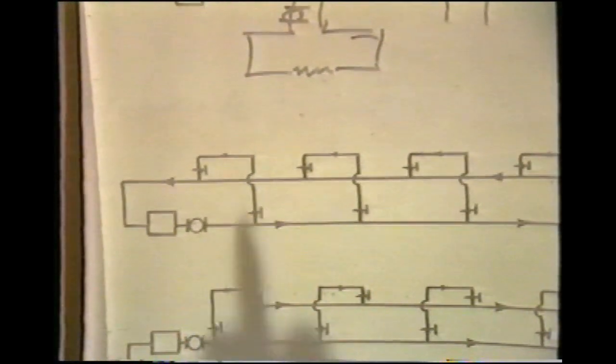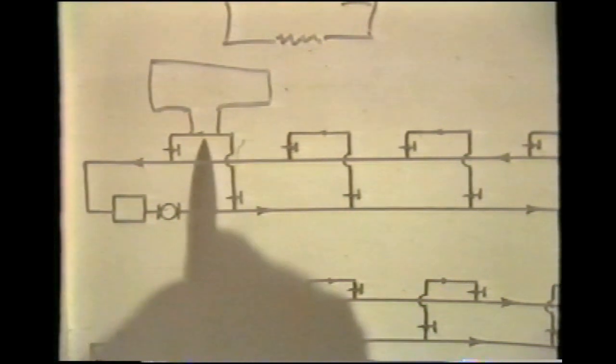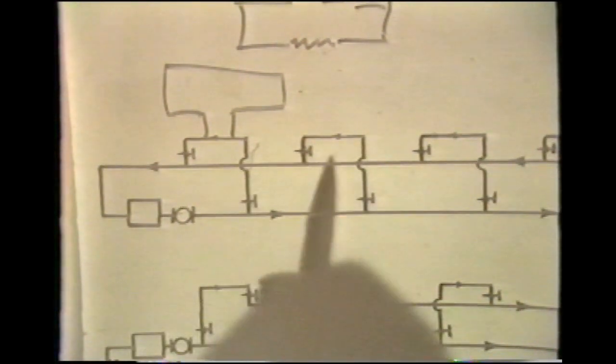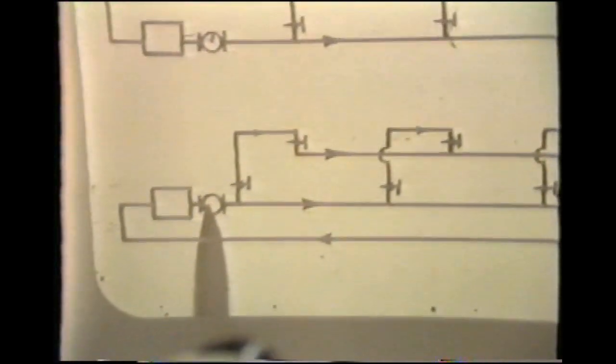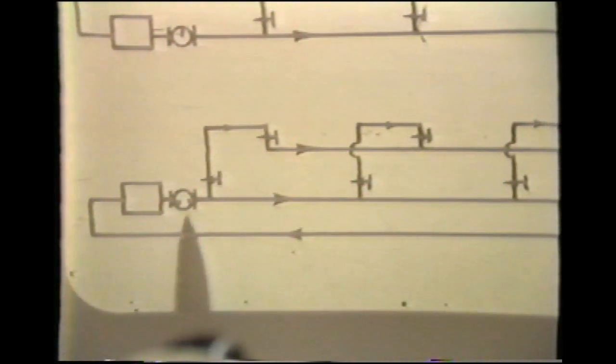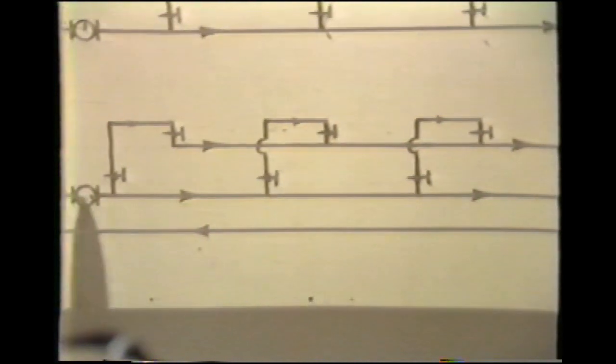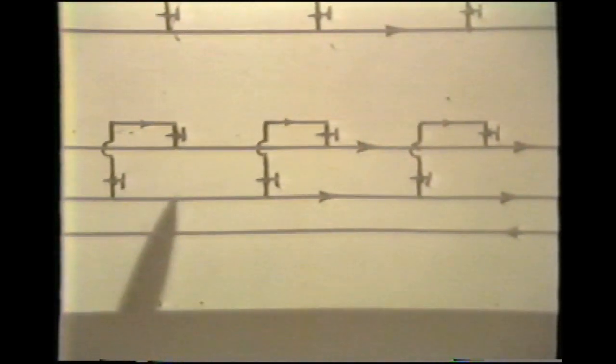The same thing applies to a two-pipe direct return piping system, in which we have crossover bridges. And the crossover bridges, in terms of flow rate, are correlated with the secondary circuits connected to those crossover bridges. But it will be noted, again, that because we have very little pressure drop in the common piping, the primary pump is concerned only with distribution of the necessary flow rate through each of the crossover bridges. The same thing applies to a reversed return circuit, in which the primary pump, being disassociated from pumping of the secondary circuit, is only concerned with the development of the necessary flow through each of the crossover bridges.